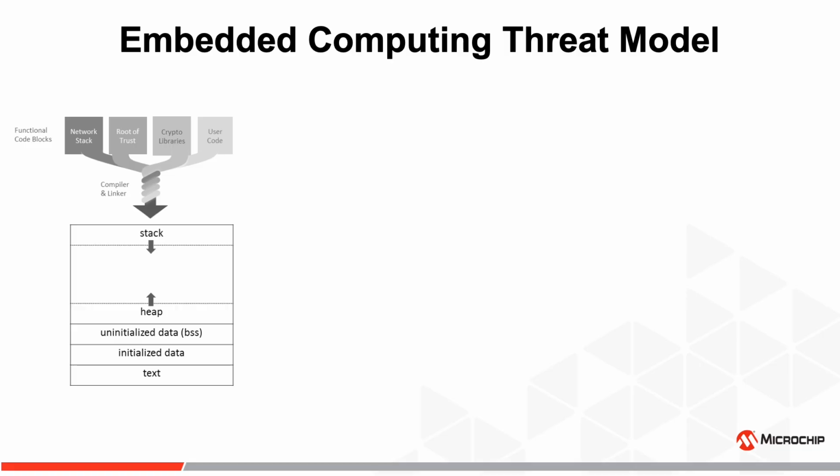So typically, if it is a connected device, it will have a network stack. And whether that's TCP/IP or Bluetooth or anything else, doesn't matter. That's quite a bit of software that interacts with quite a bit of hardware. If there is security, there's probably TLS. That's how we know security today in terms of communication and encryption. And TLS requires secrets, requires a root of trust. So the root of trust itself, with not just the hardware, but the software that runs it, which includes the text segment, the program, but also the data segment, which is the state of the program the moment it is processing secret or, in any case, confidential information, is eventually shared with the rest of the system.